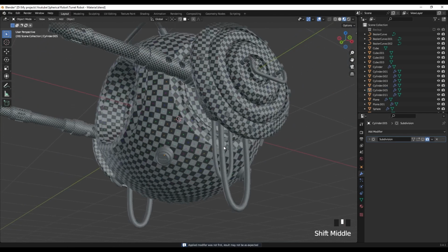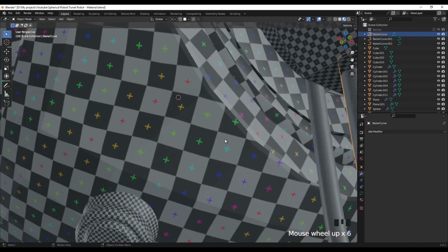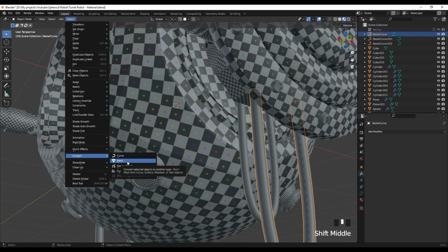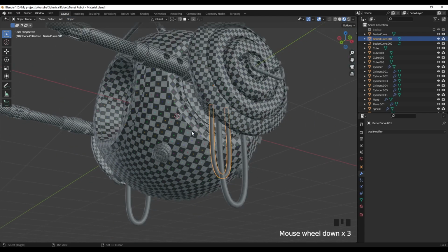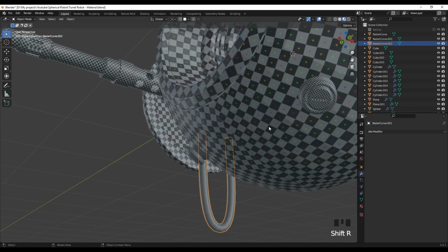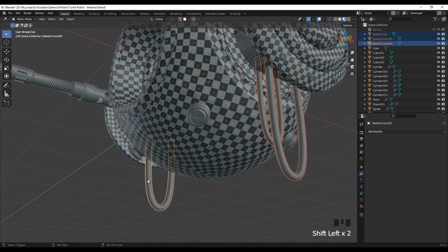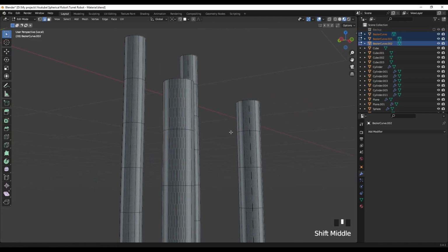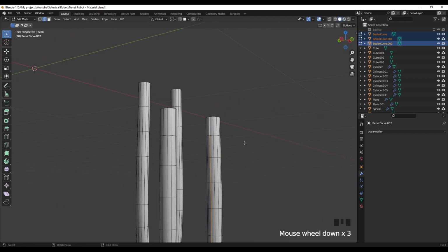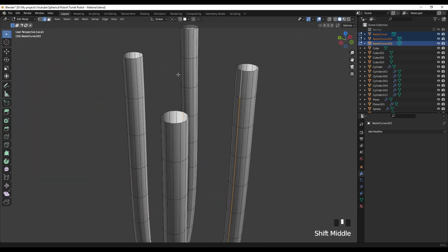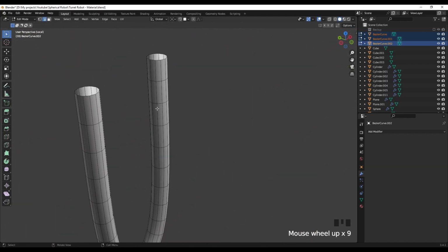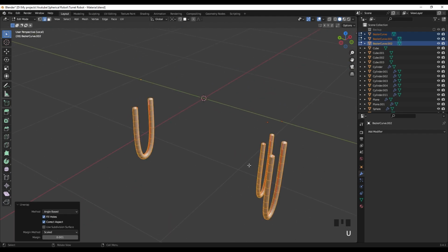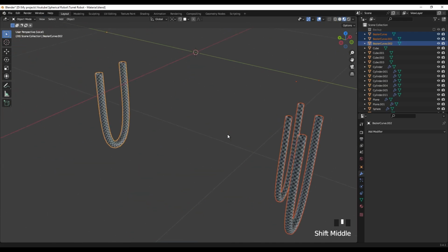Let's go back, and these wires need to convert to mesh. Convert to mesh. Shift R and Shift R, and select these. Go to isolate mode and go to edit mode and select these loops. Also here and here, and mark seam. Select all, U, and unwrap and see the result.